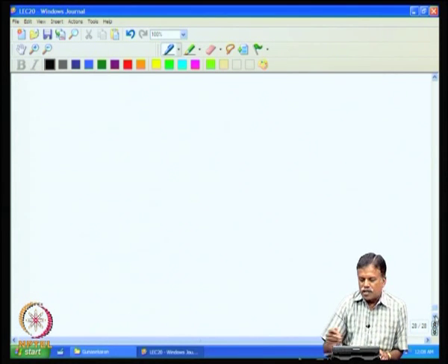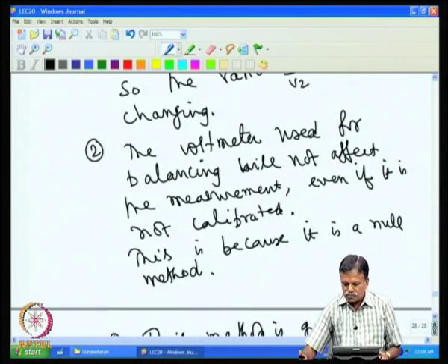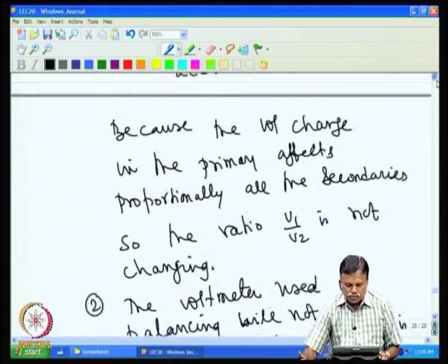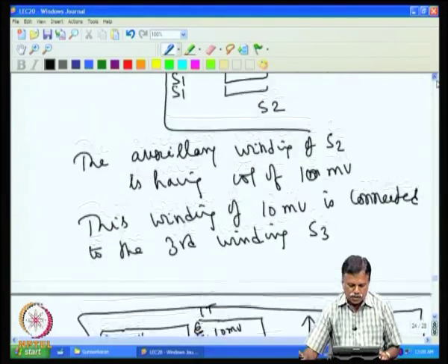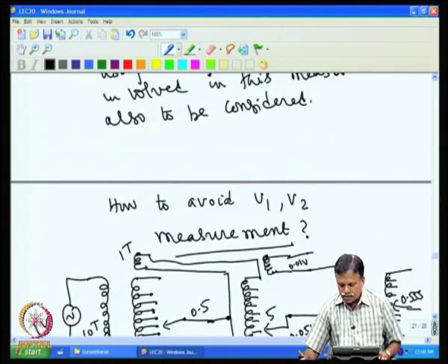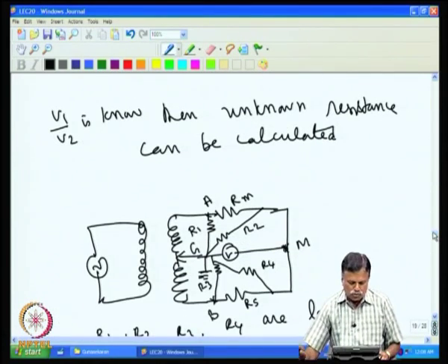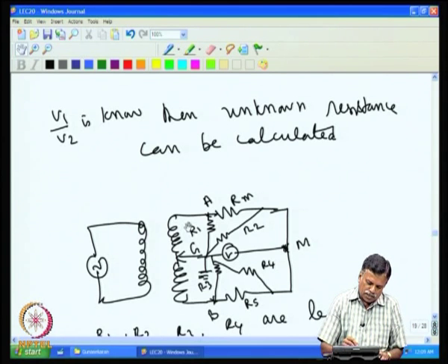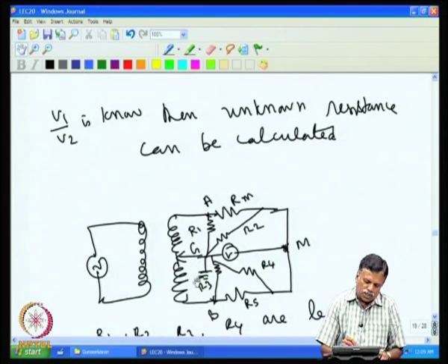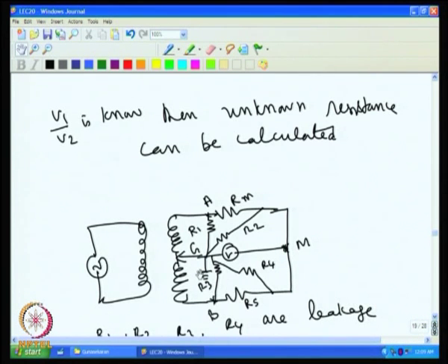If we look carefully at the ratio transformer, all that is required is that we produce two accurate voltages, V1 and V2, which are only 180 degrees out of phase, and then I should be able to vary V1 and V2 such that the balancing is done. That we can achieve using an operational amplifier.